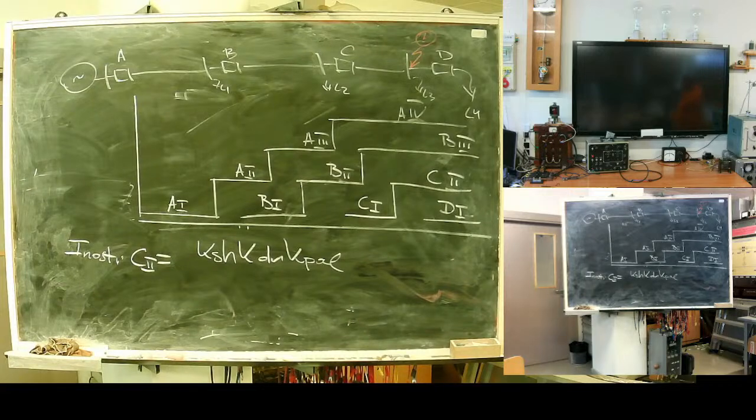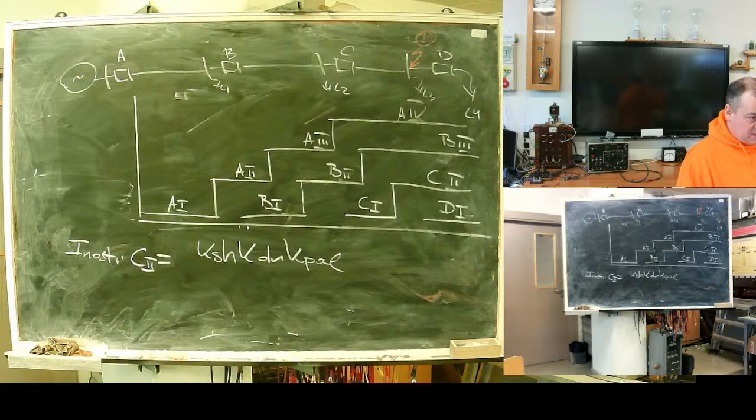When you connect your line to voltage, remember my first demonstration with current balance. What we saw was startup current and false operation on startup current. To prevent false operation, the trip setting should be increased.